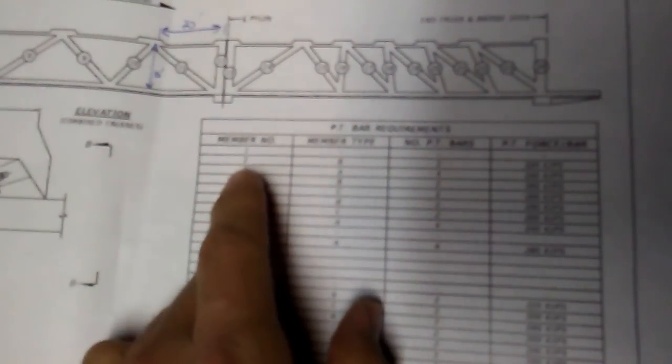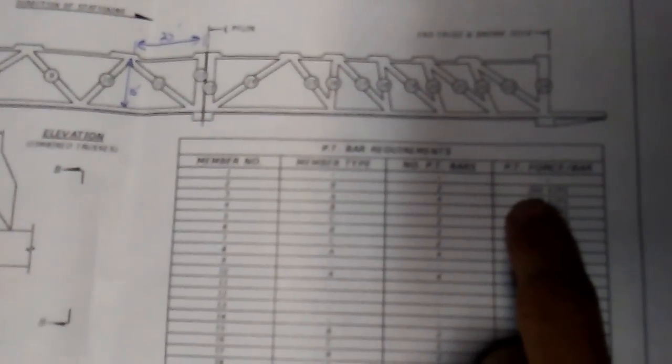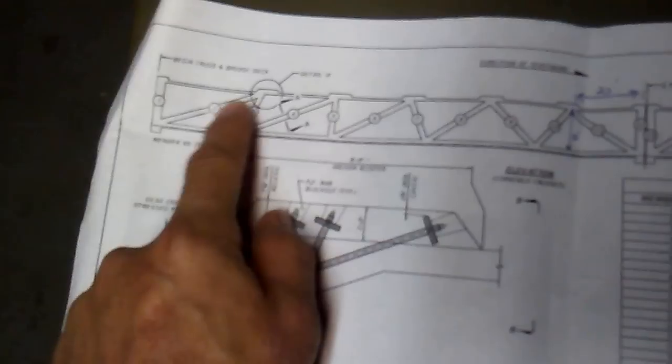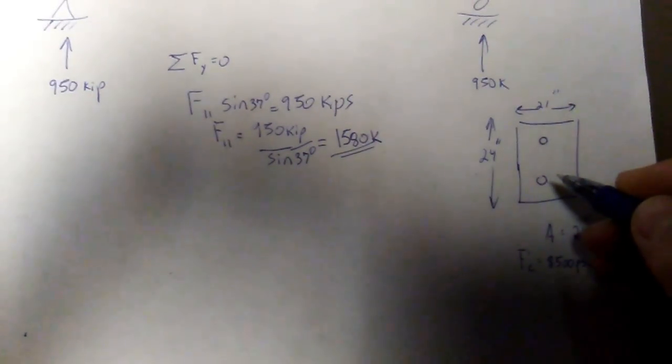All right, so I'm going to go off of the forces shown for member 2, which is 200 kips. Member 2 is the opposite diagonal member on the opposite side. It's the matching diagonal compression member on the opposite side of the bridge. So we're going to say that 200 kips is the post-tensioning force in each bar within that diagonal member. So each bar is contributing 200 kips, squeezing the member.